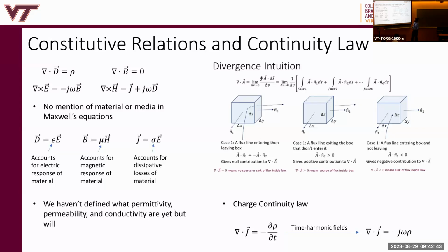So when you do that surface integral over that face, you get a positive contribution. Okay, so what does this mean? Now we understand what the divergence is. If I have a positive value for the divergence of J, the current density, then there's flux exiting that volume. That means current is leaving that volume, which means whatever charge was stored in that volume is flowing out. Current is the flow of charge, so the charge in that volume must be depleting.